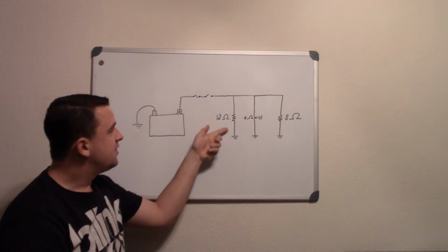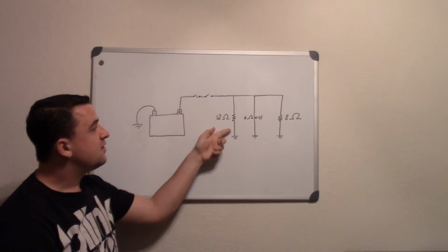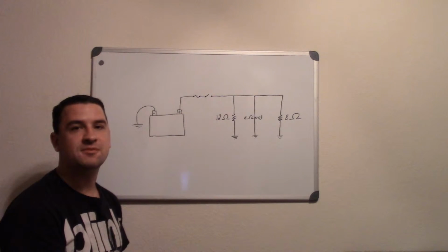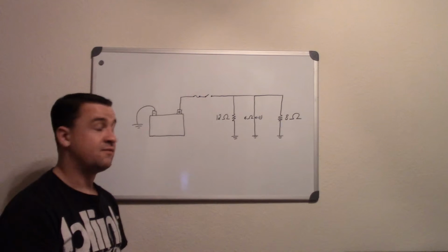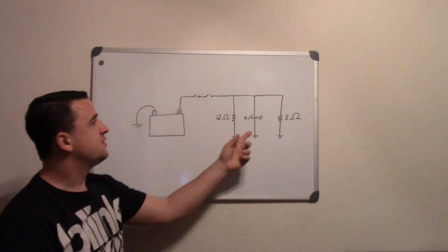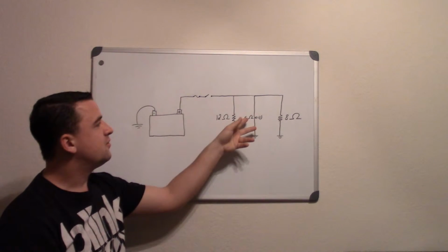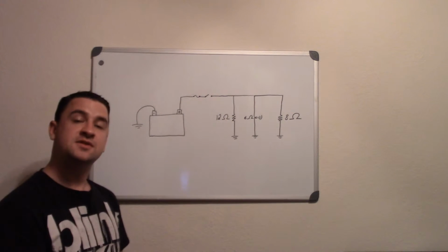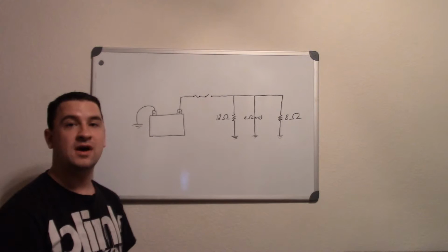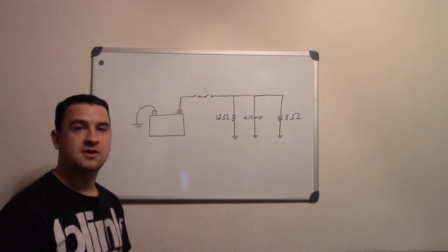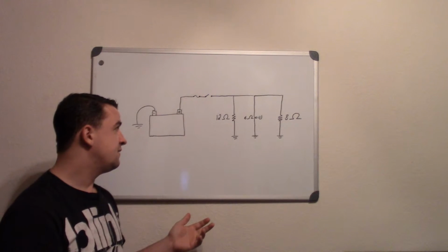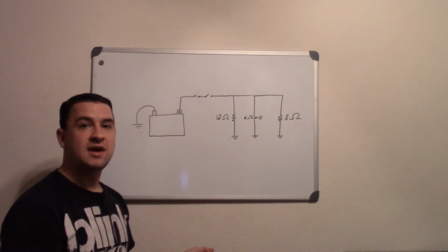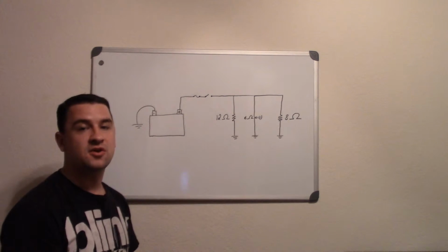Unless you add another resistor to a branch, then depending on the resistance of the two resistors, you'll have some voltage drop across one and some across the other. But if you just have one light bulb, you'll get that full 12 volt drop on that one bulb. Now, one of the positives of why we use parallel branches is that if you get an open somewhere, depending on where the open is, it may cause just one of the branches to go out.